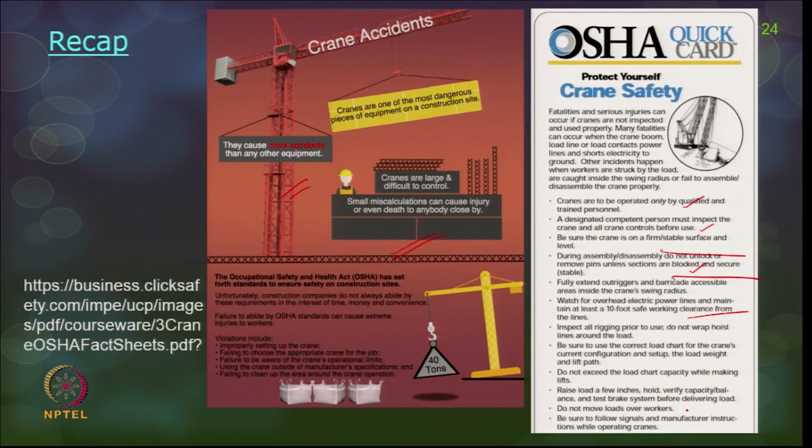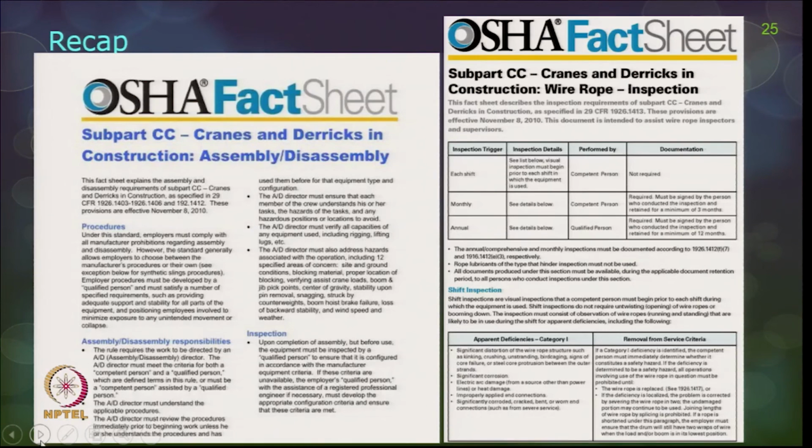Raise the load a few inches, hold, verify balance, and test all the braking systems before moving and proceeding with delivering the load. Do not move the loads over the workers. Be sure to follow signals and manufacturer instructions while operating the cranes.